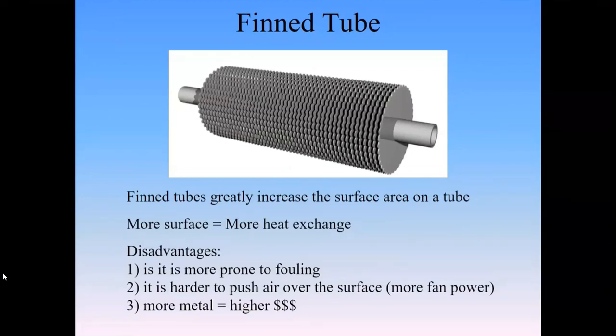And this fin tube is generally made with metal, or the fins, which allow energy to be conducted directly down into the tube. So we kind of absorb heat onto the fins, and then that energy is able to move through the fins through conduction, and then makes its way into the fluid that moves through.